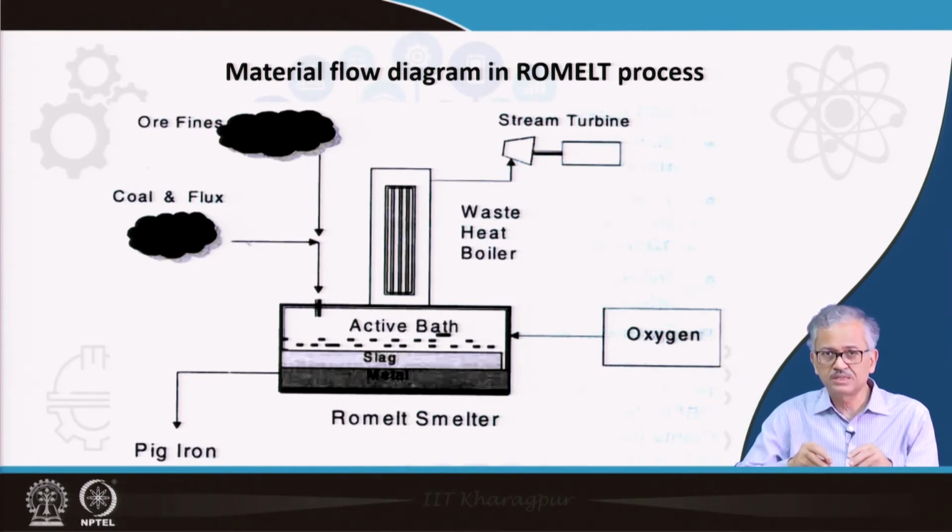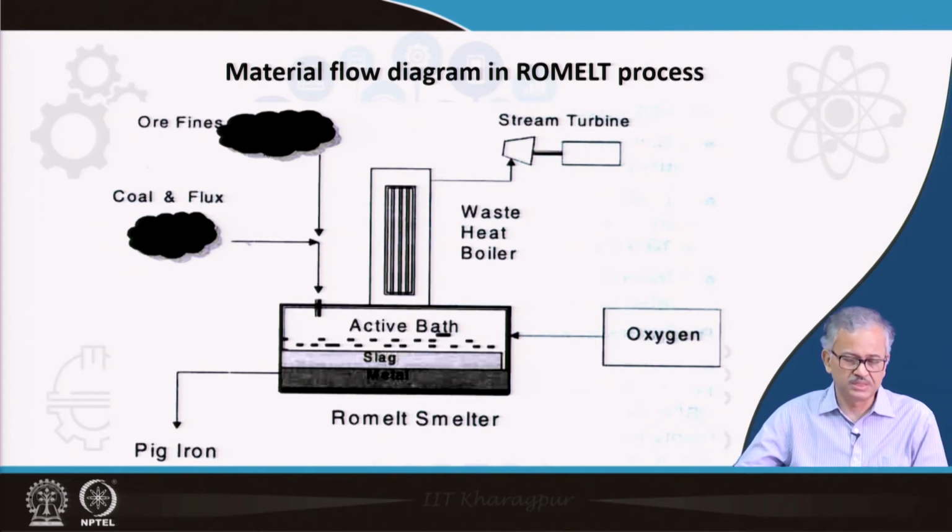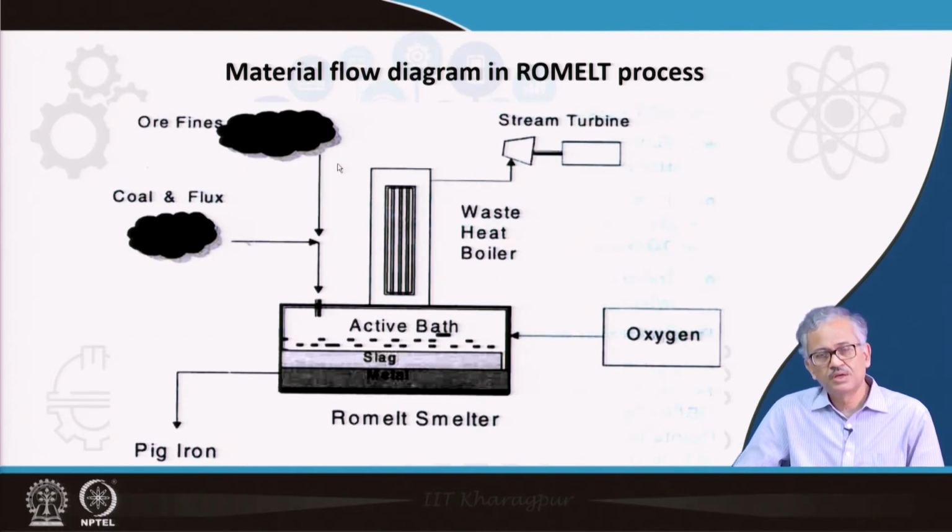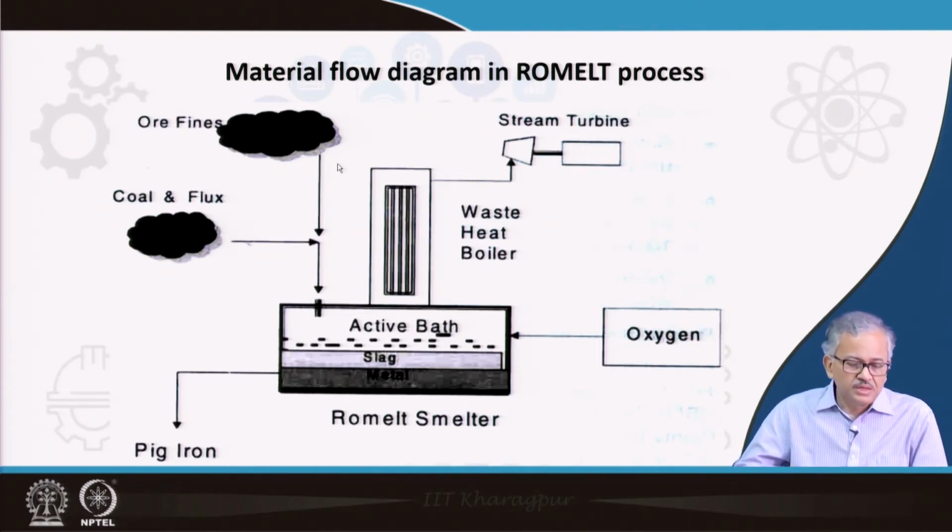In two-stage processes there are some restrictions, but in the single stage you don't have any restriction. That's why this single stage smelting reduction process cropped up, because of utilizing the iron bearing waste material from the plant. So it is not only the iron ore fines.